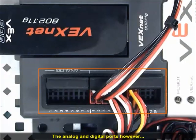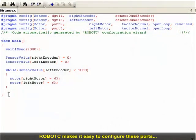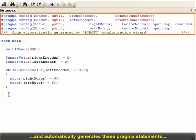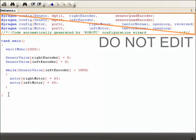The analog and digital ports, however, can be used to connect many different types of sensors, so you need to tell Robot C what sensors you have and which ports they're plugged into before they can be used. Robot C makes it easy to configure these ports using the Motors and Sensor Setup menu, and automatically generates these pragma statements, so no coding is required on your part. In fact, don't type in this section unless you absolutely mean to, because it's only meant to be set using the Motors and Sensor Setup menu.